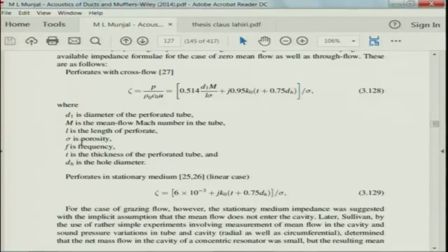One clever engineering trick people use, if they want to maintain good aerodynamic performance and get rid of the flow-induced noise due to the flow expansion, is to use a highly perforated section, 30% porosity, so that the waves are allowed to pass through very easily.